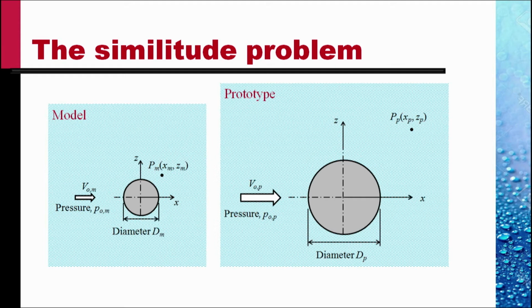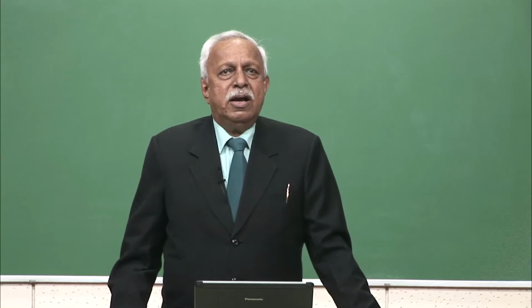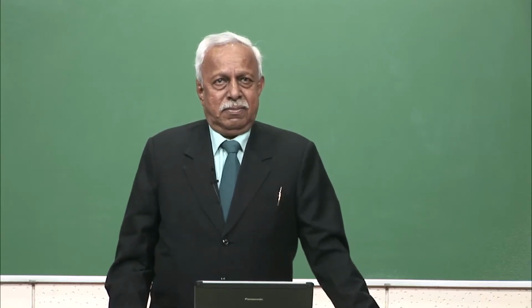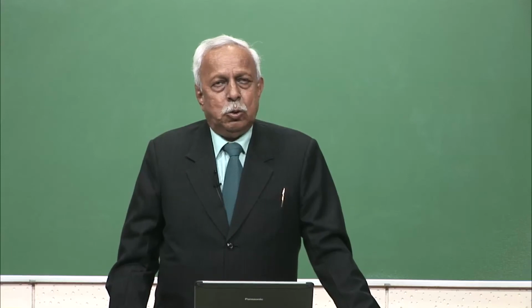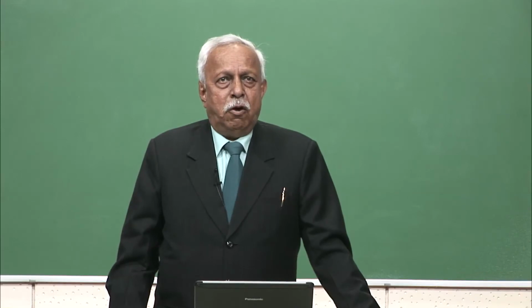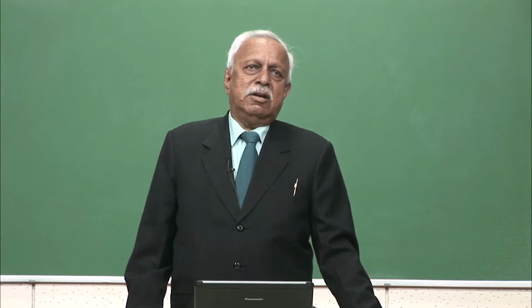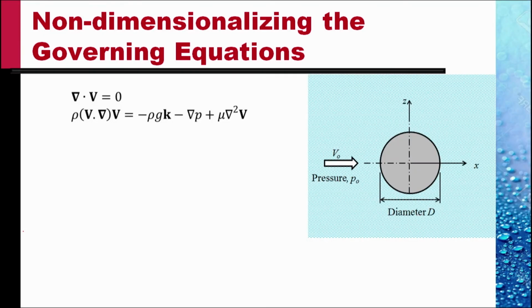The problem that we have on hand today is to determine how to ensure that the flow is similar, and once we ensure the flow is similar, to determine the rules for predicting the results for the prototype given the results on the model. There are various methods of analyzing similitude. We will start with a standard method of non-dimensionalizing the governing equations.